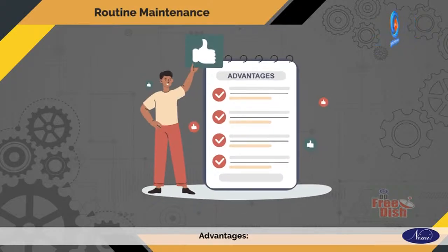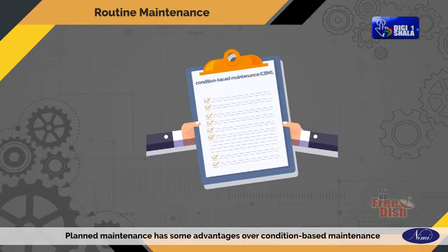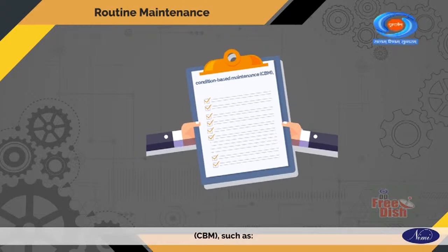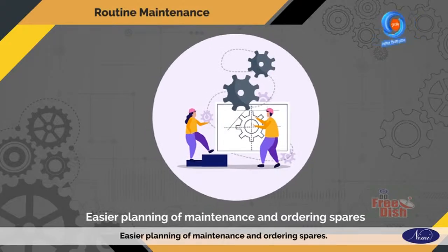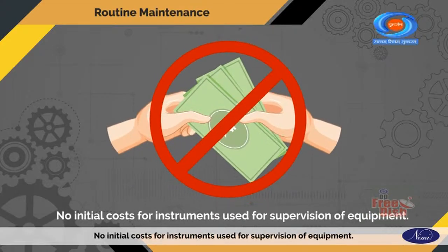Advantages. Planned maintenance has some advantages over condition-based maintenance (CBM), such as easier planning of maintenance and ordering spares. Costs are distributed more evenly. No initial costs for instruments used for supervision of equipment.